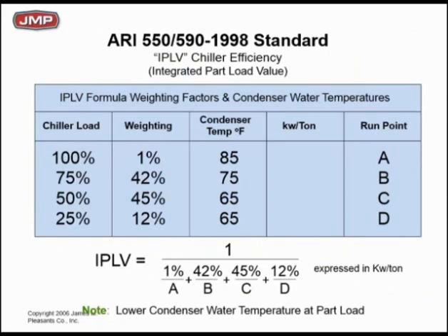You're not going to run a hot water pump wide open 100% of the time. You're not going to run a chill water pump wide open 100% of the time if you've got two-way valves that the code demands. So we're making a statement to you: we need to start looking at something other than just best efficiency point. We need to be looking at efficiencies with some kind of standardized load profile. If you know your actual load profile, great, let's use it. But if you don't, let's have a standard that everybody can use.